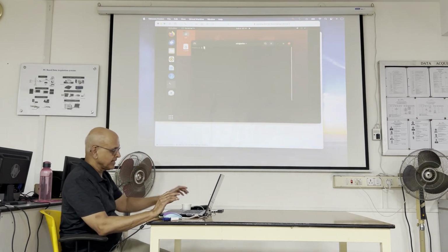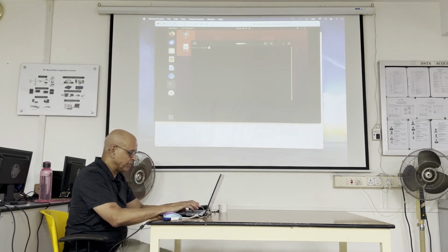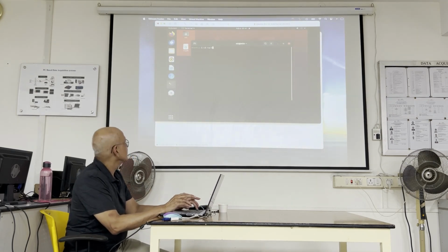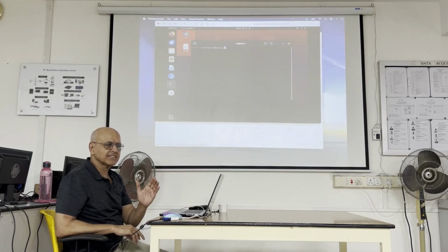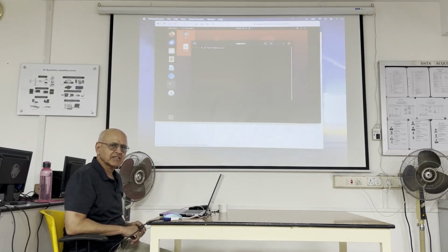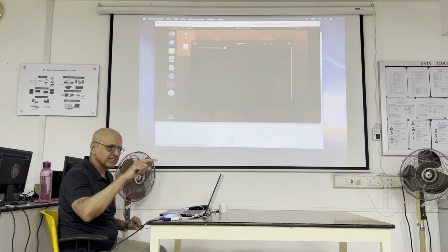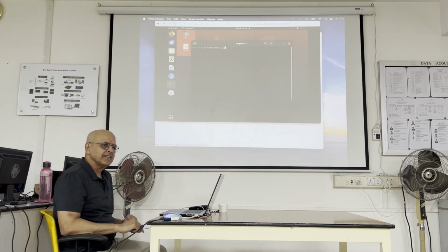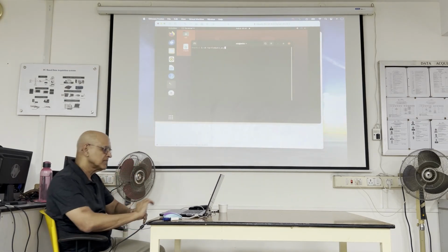This is your home directory, it is not your workspace. So you go cd, in my case it's the turtlebot3_ws. In your case it's the catkin_workspace. So you need to go to the catkin_workspace, just do ls, and you'll see the directory there. And then don't type it all out, just do a tab complete, because then it picks it up.